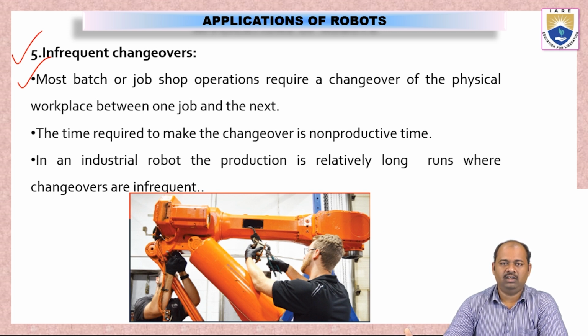We can set a number of operations that can be done by a robot in the program, and this can be used for doing multiple operations one after the other without losing any time. If I want to use the robot for a particular purpose, like loading an object into the lathe machine and unloading the object from the lathe machine, that is one set of operations.